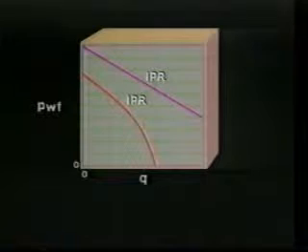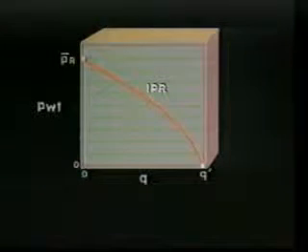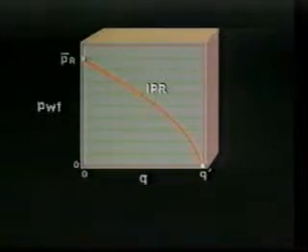The production rate as it relates to pressure drawdown may be a linear relationship or, more commonly, a nonlinear relationship. Where liquid and gas phases exist within the reservoir, flow rate and drawdown are not linear, primarily because of the relative permeability properties. In addition, the inflow performance relationship of a well will change as reservoir pressure is influenced by depletion or enhanced recovery projects. For further discussion of inflow performance relationships, the viewer is referred to modules PE 102, 103, and 104.